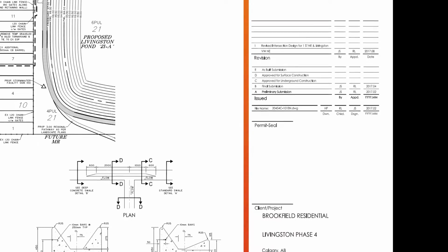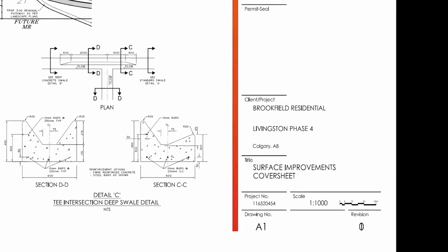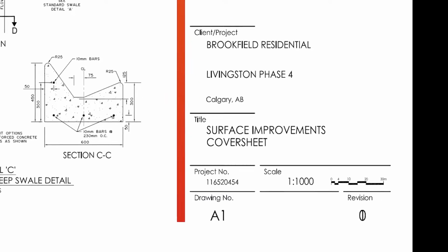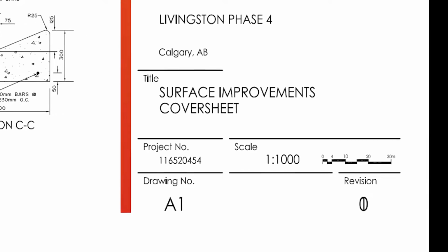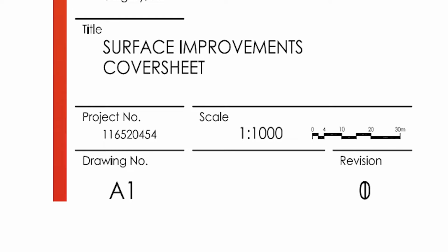There is a space for the engineer's official seal or stamp. It is very common for the bottom right of the page to have the page title and page number. This makes it easier to locate a page when flipping through the pages of a large set. Finally, you see a scale. There is a ratio and a graphical representation of linear measurements. On a properly scaled printed set, you can use the ratio and a scaling ruler to measure distances. Alternatively, the graphic is helpful to get approximate measurements of features on the plan. Some engineering firms place this info along the bottom of the page, but you will notice the information is very consistent from project to project.